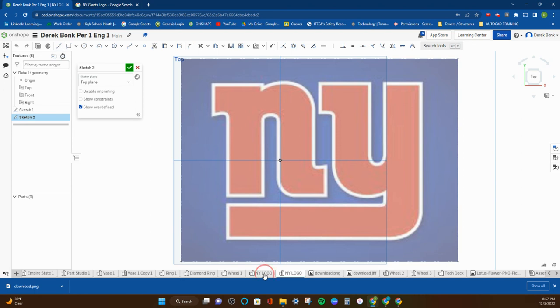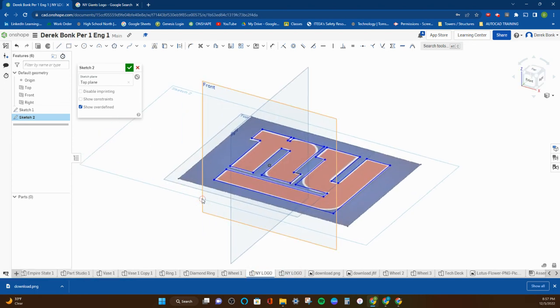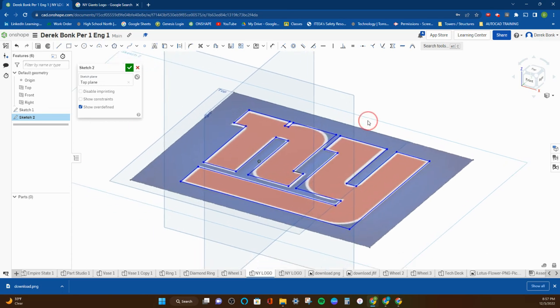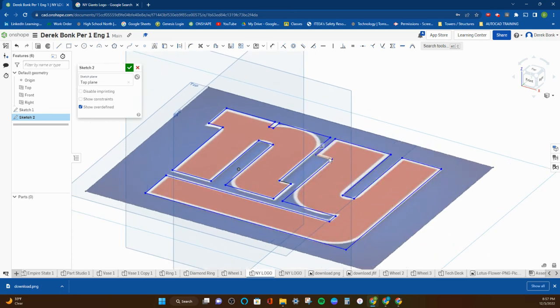Now, if I go back to this previous preview, you'll see that I use straight lines, even though there are certain places where a lot of curves exist. That's because when you're dealing with the sketch tools, you're looking at all these different options for how you can go about tracing something or drawing anything in general. You can go back and modify 90-degree angles with what are called sketch fillets. You can click on that and you can go back in here and let's just do this quick and simple.